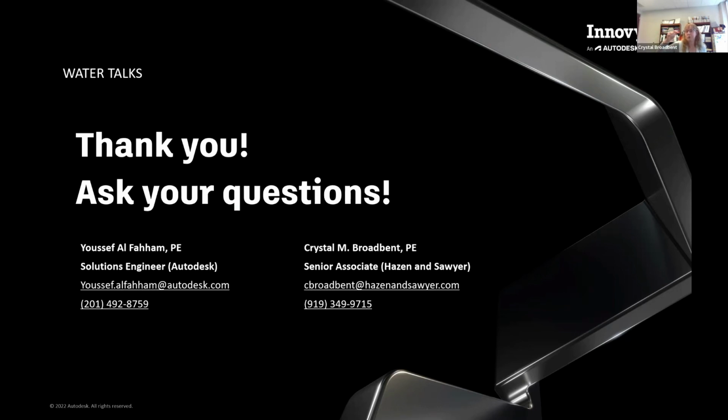And so the data sets, like the control set, will tell you if the pump's on or off. That does play a role in surge, but the surge icon for the pump will also tell you if the pump's on or off. So if you have the pump off in the control set, but in the surge set, you have it as a 1, like, hey, this pump is on, that's going to override the control set. So there isn't ability to have data sets yet for surge. So you got to keep that in mind. I have a model that I've been using for different pump stations. You have to make sure that you've turned off the other pump trip when you go to trip another pump. Otherwise, they're both going to trip.